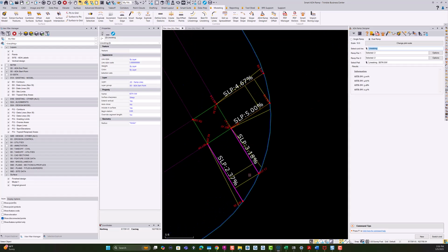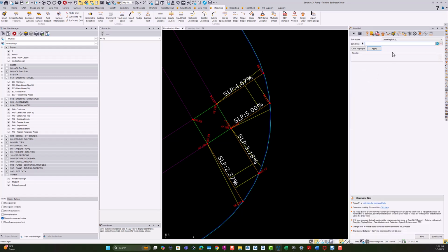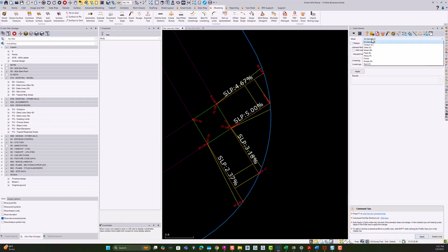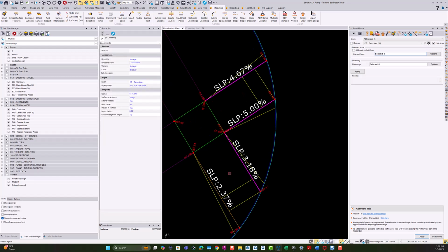If you now want to elevate other lines on this intersection, you could switch mode here to the Smart Edit command, which is in the header bar of the commands. And when you run Smart Edit, you can now pick the elevate lines, sorry, not intersect, I want to go to elevate lines rather, so go to Smart Elevate, and in Smart Elevate you can pick the intersection mode, and intersection mode basically allows us to pick the lines that are intersecting. So in this case we're going to say these are the lines that are already 3D that we already know the elevations of,